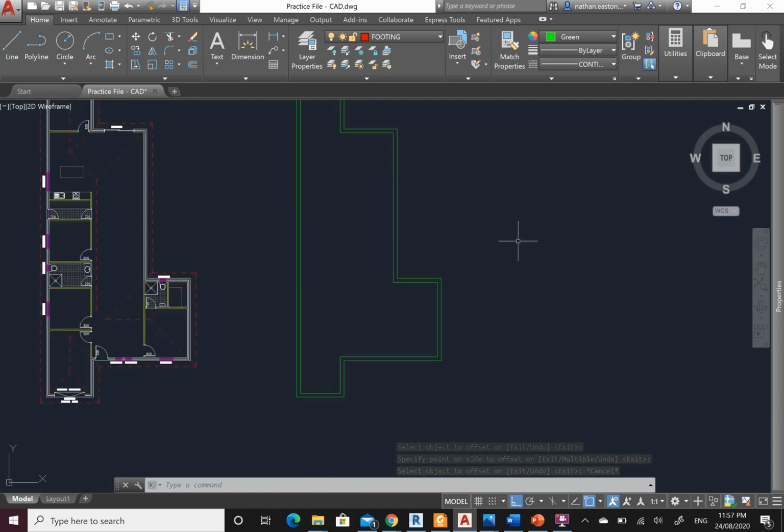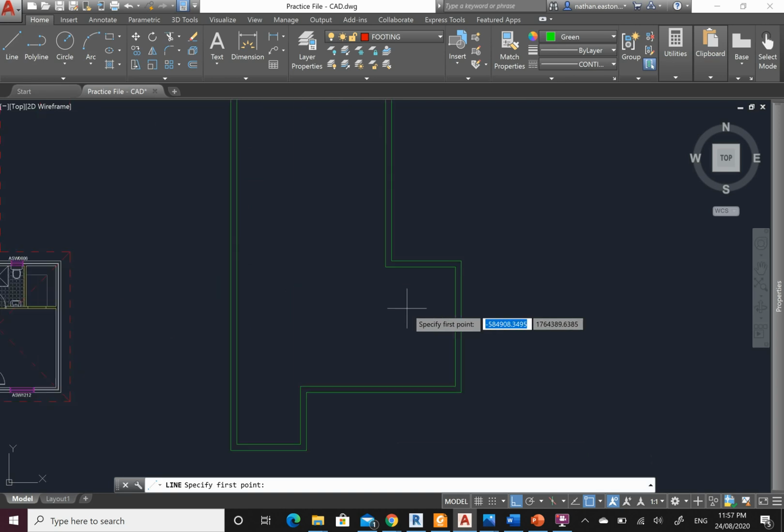Now what I need to do is put in my continuity, which is a big thing. Everything has to run into a grid. If we get this wrong, that's when buildings start to crack, and the purpose of these foundations is ruined. So straight away, all of my corners, I just make straight lines right the way to the edge.